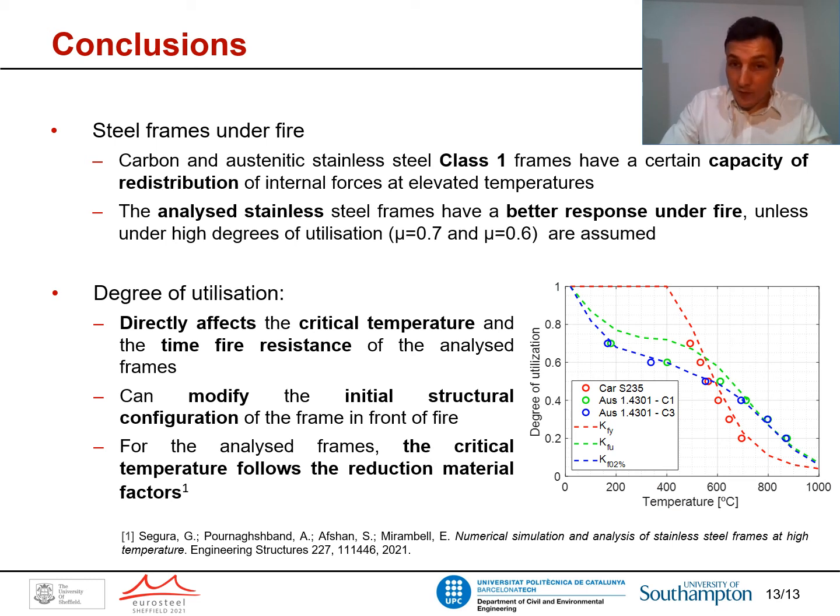Regarding the main topic of the presentation, the degree of utilization, we would like to point out 3 highlights. First, the degree of utilization has a direct influence on the critical temperature and time fire resistance of the analyzed frames, as was expected. Second, it can modify the initial structural configuration of the frame for very high initial loads, as was shown in the last slide. And the last one is that the critical temperatures seem to follow the reduction factor of the material properties.